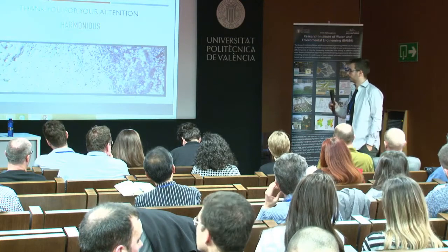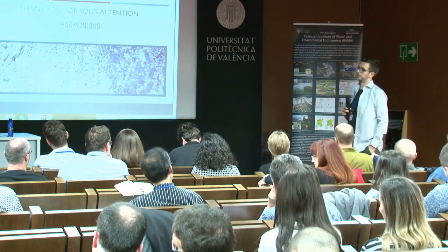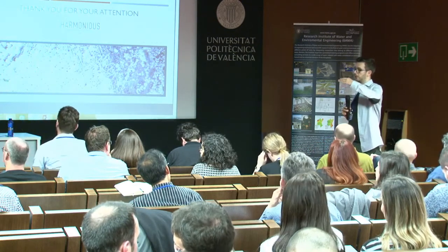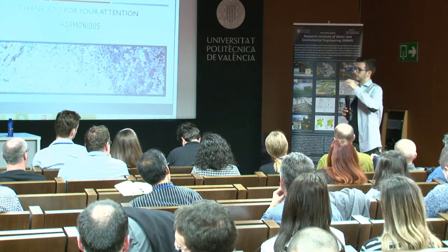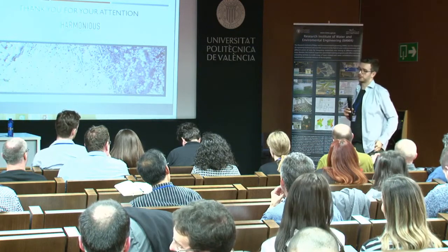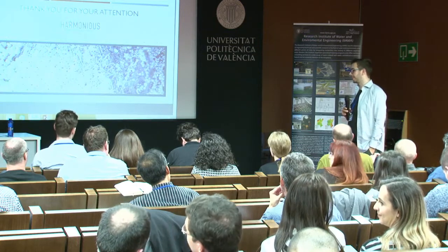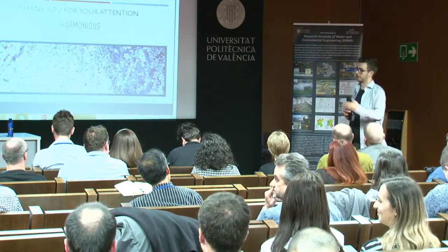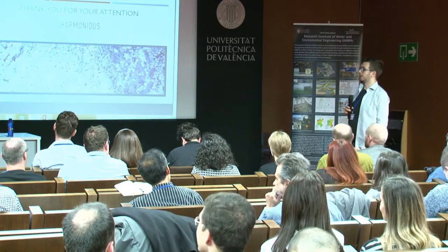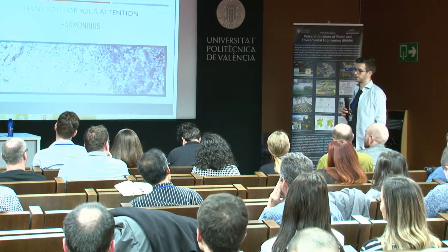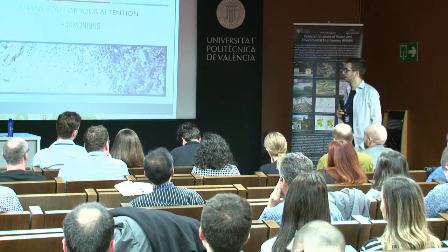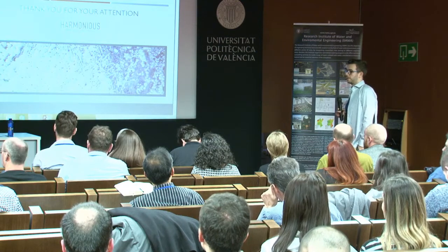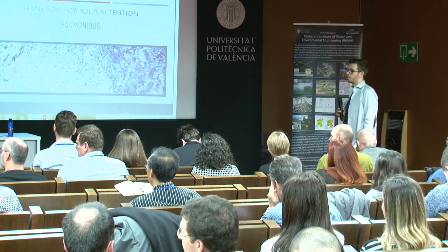We have found out in the study that 5 control points are enough, and when you are increasing per hectare, you are not getting any benefit. But if you are not going to find these 5 points in the area, I don't know, under some tree or something, then you have a problem. But if you are going to identify these 5 points, it's enough. But with real-time correction, I can say right now, based on the preliminary results, you don't need any of that. But 5 independently from the extent of the area?